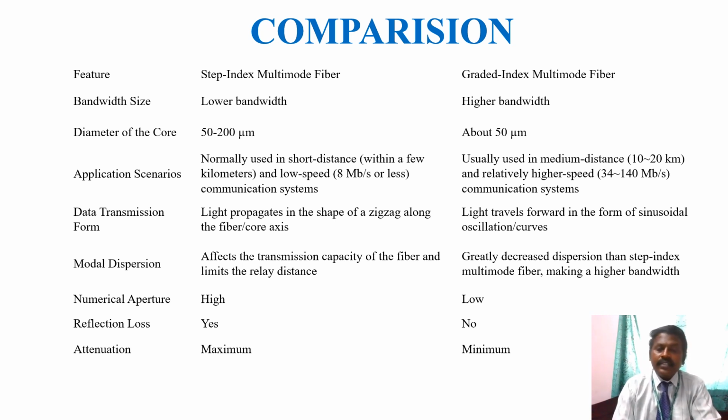The reflection loss is there in step index fiber, and the reflection loss in graded index fiber we cannot say is low, I mean it should be very low. Then attenuation is maximum in step index multimode fiber. Here the attenuation is minimum in the graded index fiber.